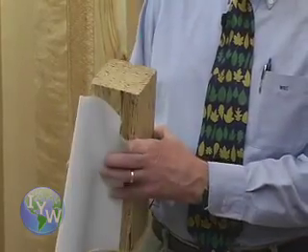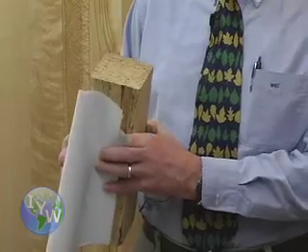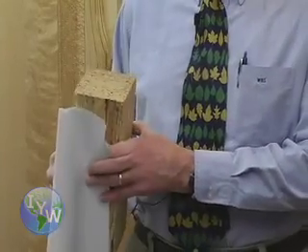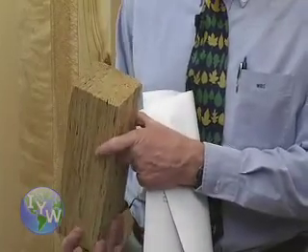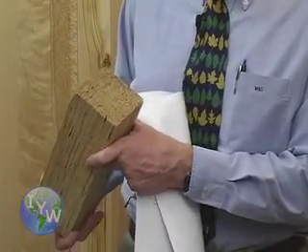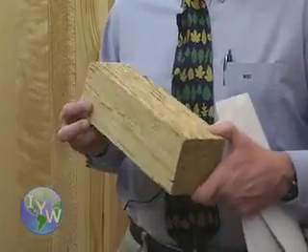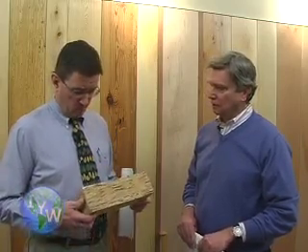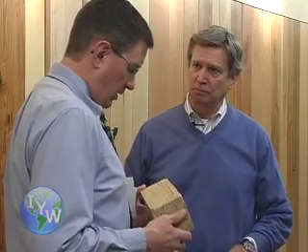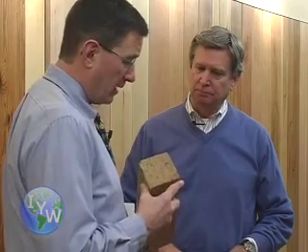And then adhesive is put on them, and then they're extruded into a machine and cured with microwave energy, such that it will come out as a timber much larger than this, maybe 8 or 10 inches wide and as deep as 20 inches. And that gives us a manufactured timber that will perform actually better than large timbers that were taken from trees in years back. So you don't have to go after the large trees. This actually is stronger. It's more uniform, and from an engineering perspective, the properties are much more predictable.